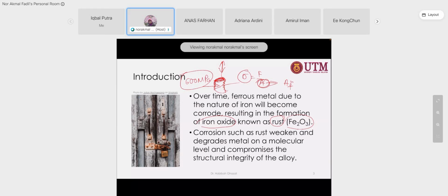So that's the reason, as a corrosion engineer, they will monitor the thickness of the structure, if it is a plate like a ship hull or any structural body, or what else? Let me think. Pressure vessel. If there is degradation in terms of thickness, the structure won't be able to support as high a load as the initial design. So if they monitor the dimension and it decreases, they have to limit the load.